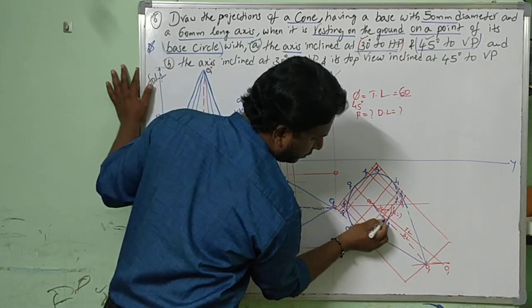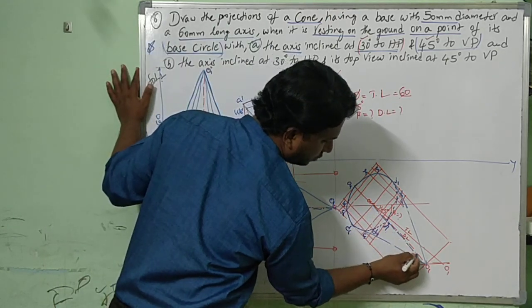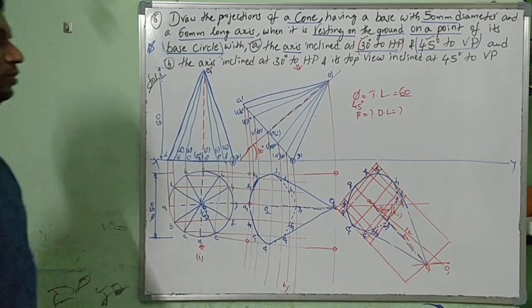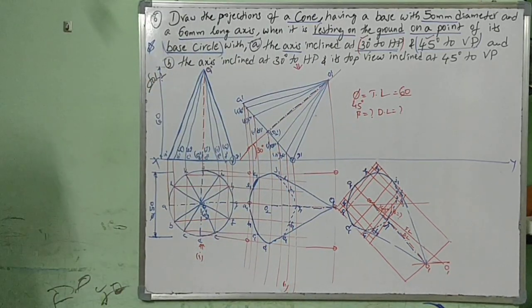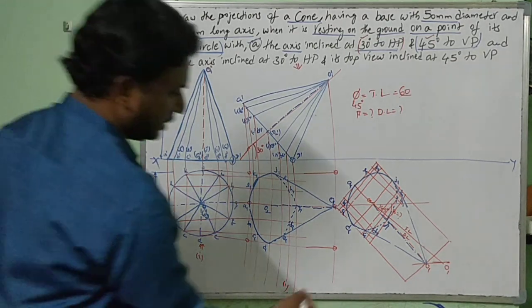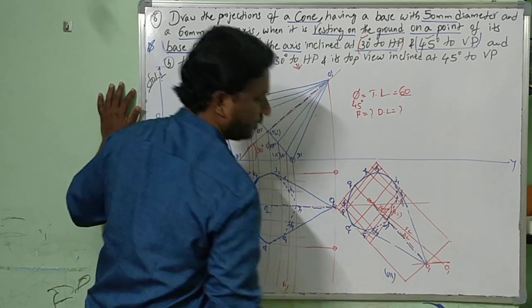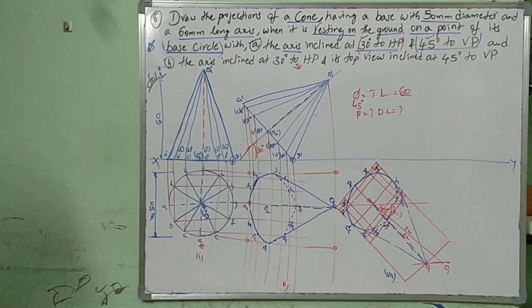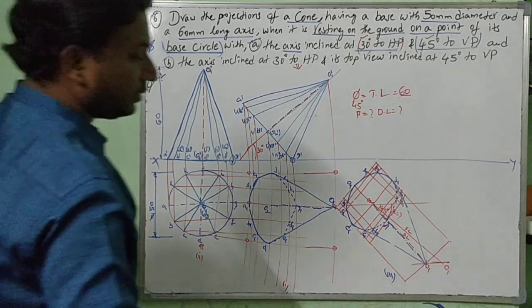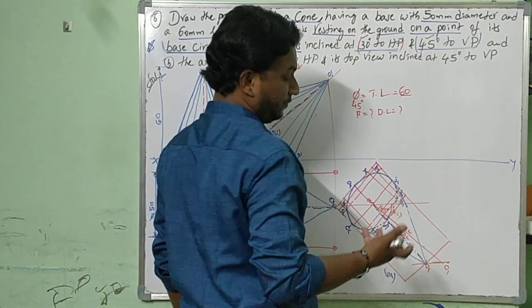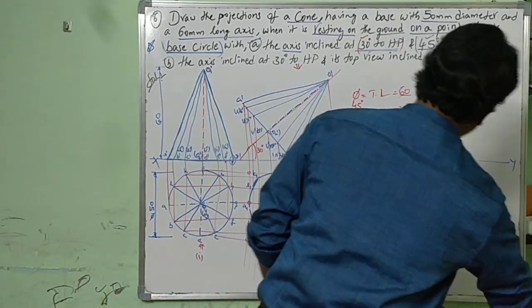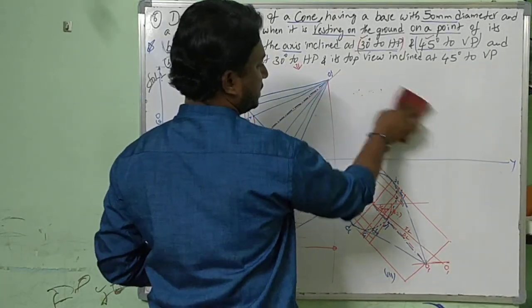Axis, already I have drawn, but still with blue. Just rotating the second stage top view to the third stage. See here, third stage, right? But for an angle beta, you should not draw it separately. You should do it in the same place. Now from here, projecting the front view. It's something typical. For all this information I am erasing.